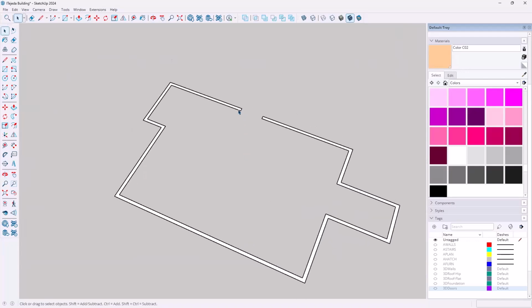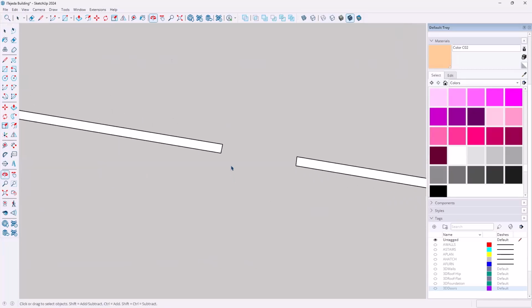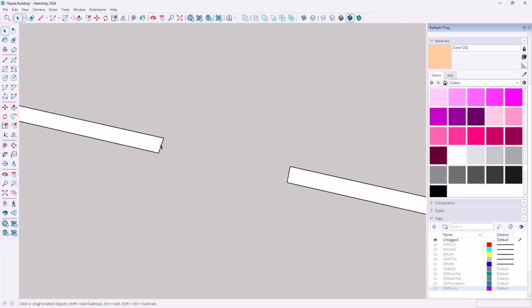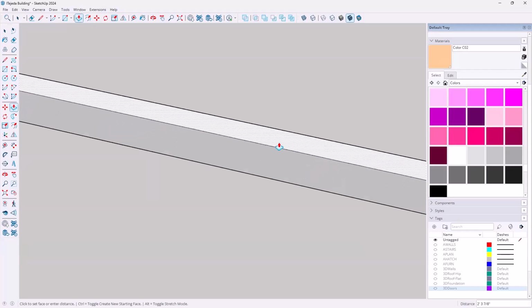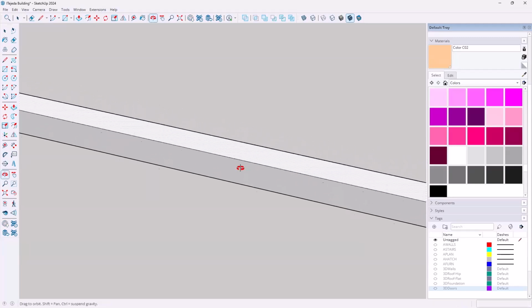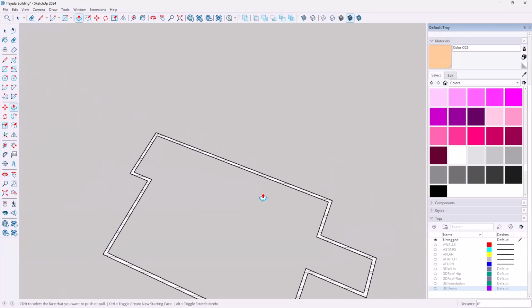And I'm seeing that I do want that wall to go across. So what I'll do is I could draw a rectangle, but instead I think I'd like to take that line, type M, and move it from that endpoint over to this endpoint like this, and then type E to erase that line. And I know that if I push pull this, watch this, P for push pull, and I take it up, I thought I would get a line there and I'm not getting one. Fascinating. That's great. Okay. Just wanted to point that out. And I was just thinking ahead and I'm glad I was wrong.